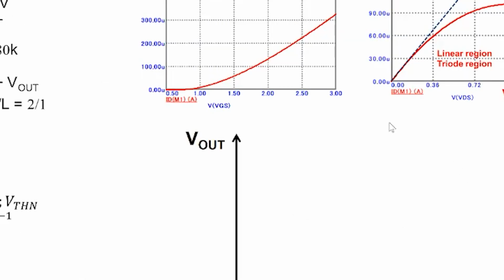All right, as a last example, let's look at a circuit which is of interest to us because this leads us to digital circuits. It's a similar kind of circuit here with a supply, RD, and a transistor, and what we are looking for is the V out versus V in characteristics. So what it means is we'll start V in from 0 and go all the way up to the supply voltage, which is 3.3. And what we would like to know is what happens to the relationship between V out and V in.